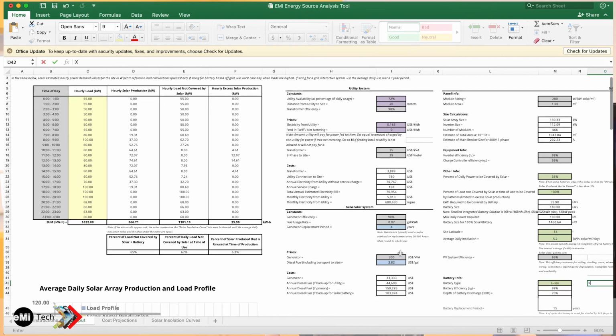We'll also enter known details like the cost for diesel fuel in dollars per gallon, utility power, where you're going to talk to the utility and look at electrical bills, the feed-in tariffs, the utility availability, we talked about what that means, as well as the generator lifetime, which we calculate as usually 20,000 run hours, and then just divide by the number of hours you're expecting per year to get an estimate in whole years. And these are where those entries are at. All of the places that you're going to want to change something are a colored cell, like purple, green, or blue, I think.